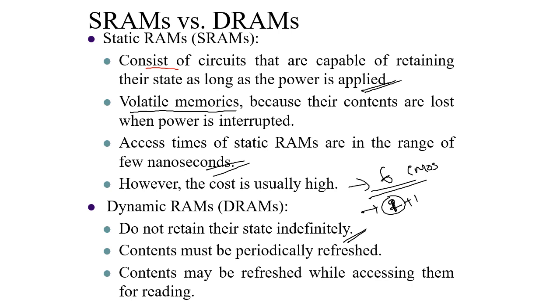When you design a system with low cost, and if the speed is not a concern, then you can go for dynamic RAM, whereas if you are very specific with the speed and access time, then the static RAM is the best choice as compared to the dynamic RAM.